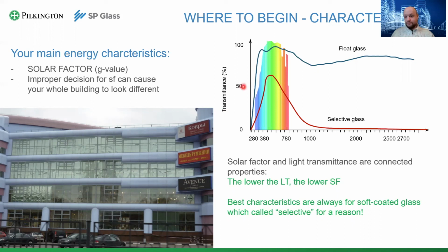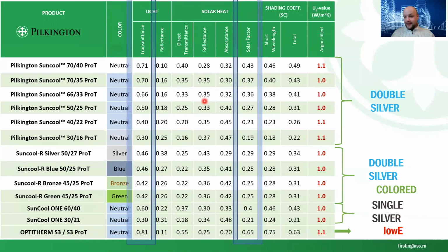Right. So I'll advocate for Pilkington glass products, not because I'm working for Pilkington, obviously, but because the characteristics are rather good. Solar control is the top priority of our glass, because that's what it is made for. That's its main purpose. So to finish up with solar control, again, if you're using something for the roof or overhead glazing, consider lowering the solar factor, I would say about 1.5 times at least.